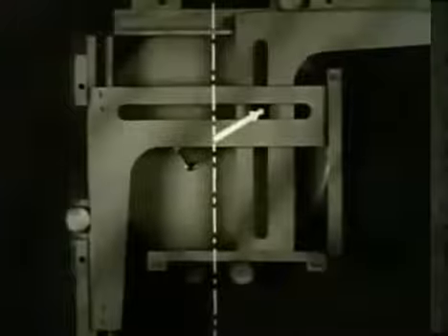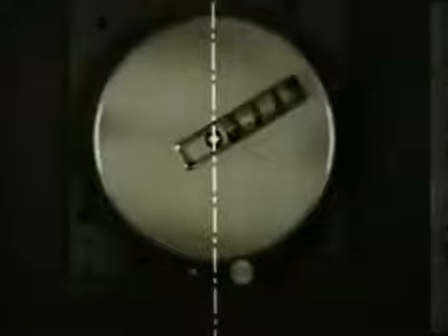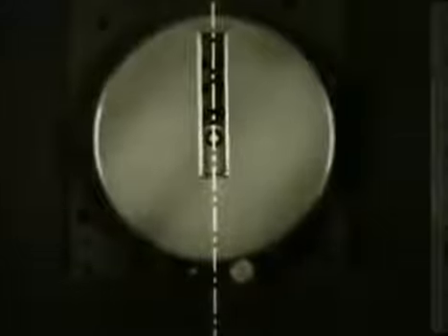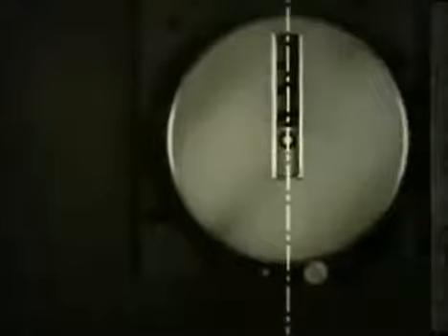To see how it forms the vector diagram, we'll start with the speed vector, considering first its direction. Direction is measured relative to this center line, which represents the line of sight. The speed vector lies along the slot in the vector gear. An input gear turns the vector gear. Direction of the slot relative to the center line reproduces the direction of ship's motion relative to the line of sight.